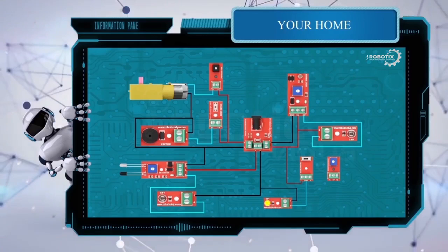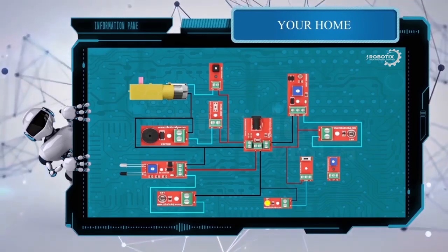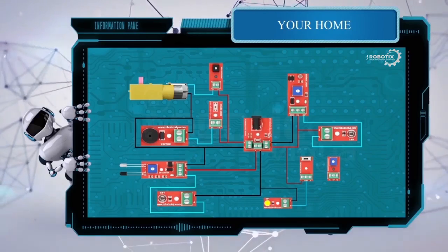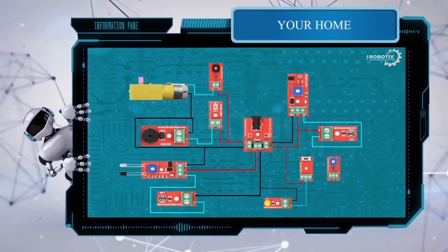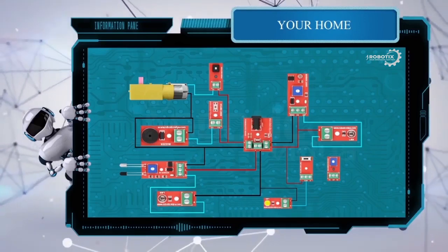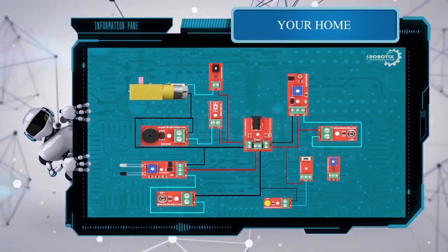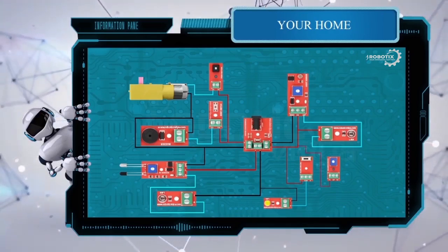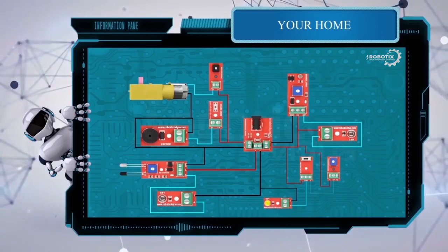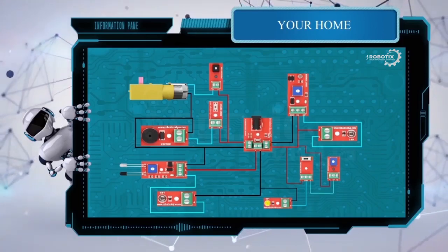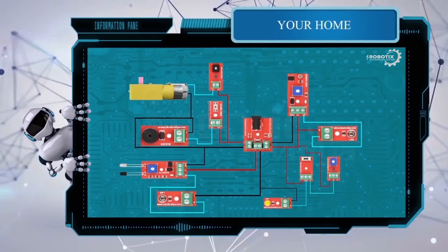Now when the switch is in position A, the LED will glow at a maximum brightness. Now the next step is to make it glow at half the brightness, and the switch is in position B. For half the brightness, we will be using the potentiometer. Connect the positive of a power supply board to T1 of your potentiometer. The output should be connected to the B terminal of your two-way switch.